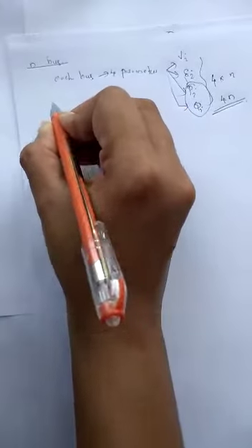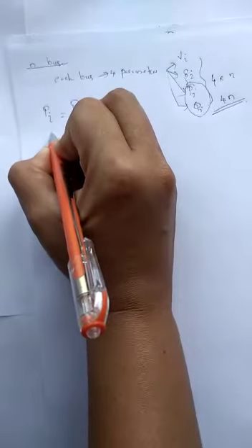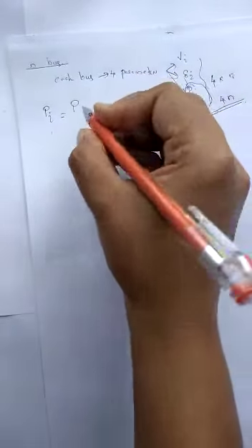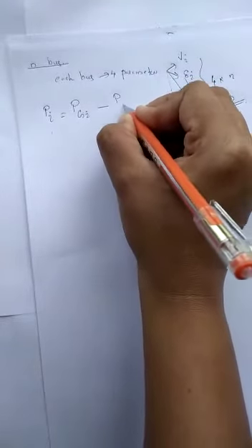Pi, the active component of the ith bus, is equal to the power generated minus the load or demand. Suppose we have a generator and a load connected at the ith bus. The total power emitted will be the generated power minus the demand power, and the rest is given to the rest of the system.